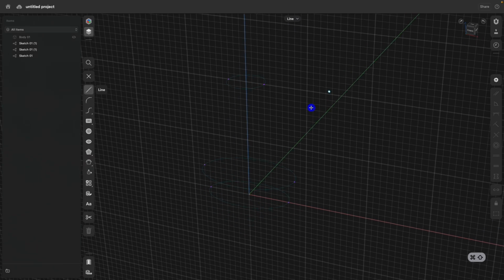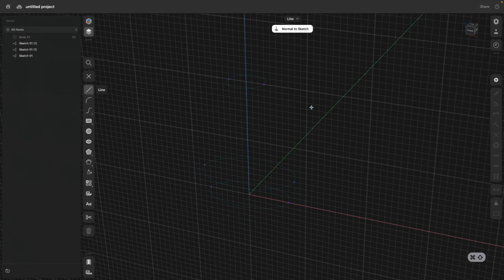And when I rotate my view, you see the grid, how it's positioned in 3D space and how it cuts actually all 3 ellipses. And there I have these magenta points. These are actually the intersection points of this new sketch with the 3 previous sketches. So the order is actually very important. I make my lofted profiles and then I draw my rails.